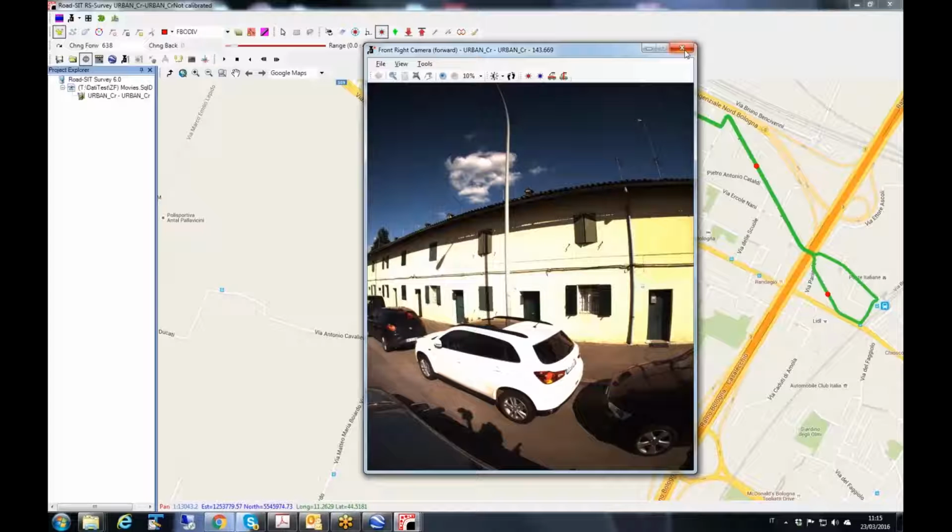You can import. So I can't take off the Ladybug from the car during a survey with our installation, no. We can discuss preparing a different installation and put the GNSS antenna on another side, not linked to the Ladybug. At that point, you can move the Ladybug. You stop your survey, unmount the Ladybug, and go where you want with it. After you return, put it on again, and you can continue surveying.